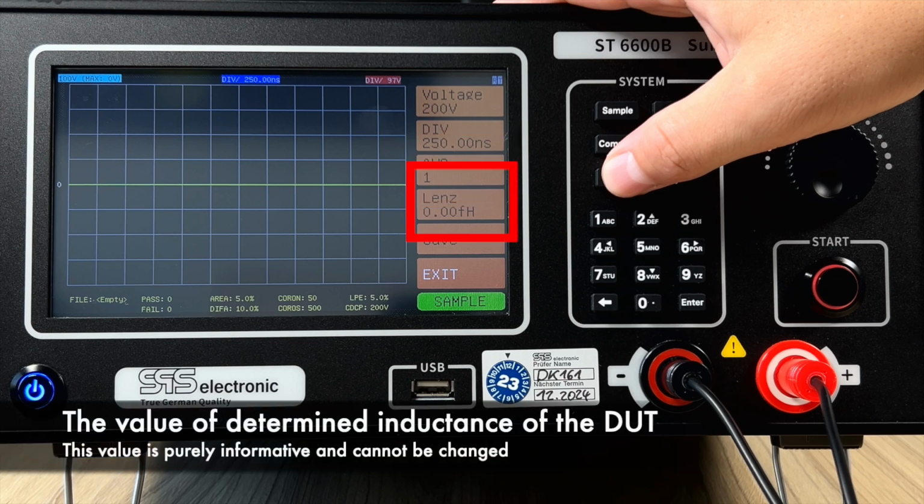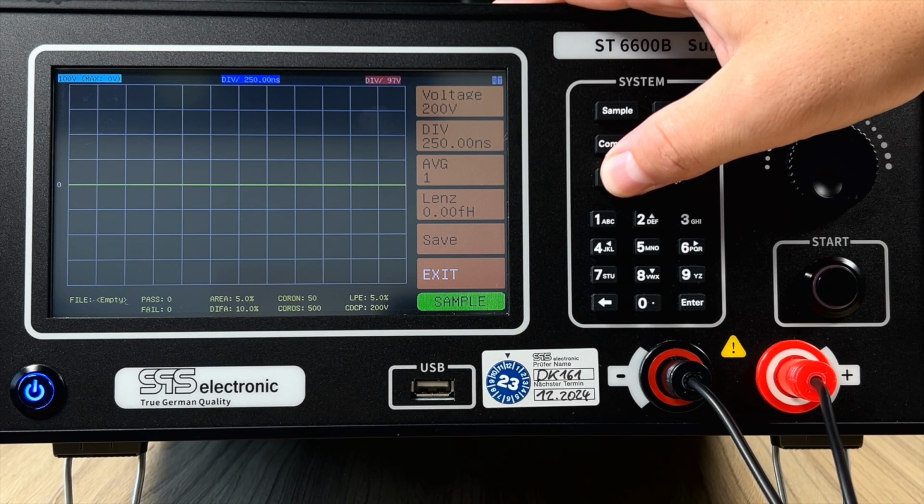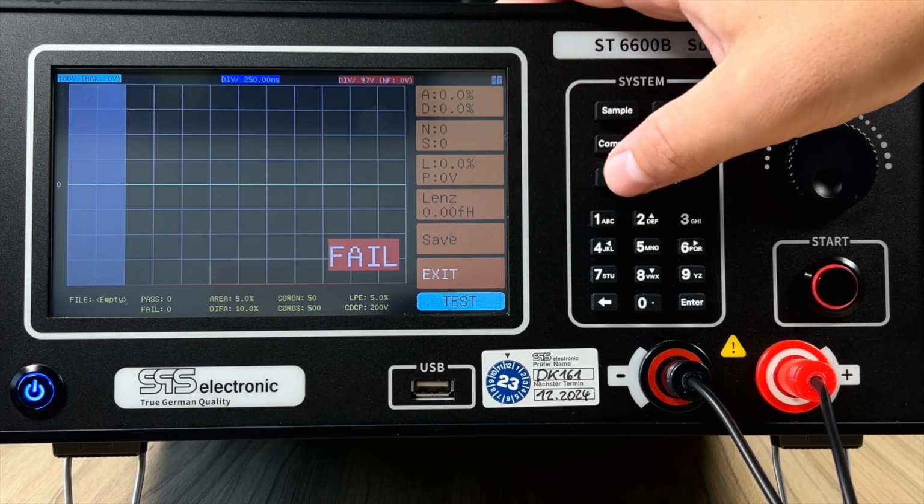For the LENS option, after recording the master curve, the determined inductance of the DUT is displayed. This value is purely informative and cannot be changed. After everything is set up, don't forget to save the master curve. The next one is the test option, where we will compare our master curve with the next DUTs. I will show you this later.